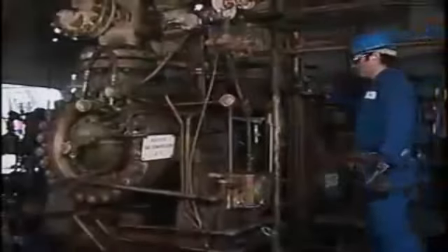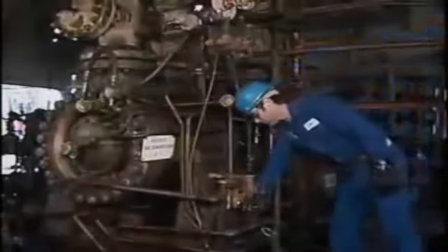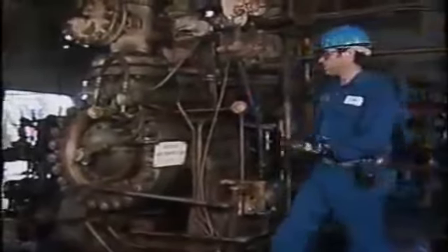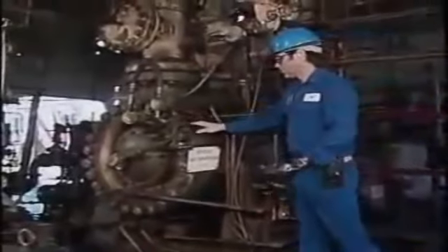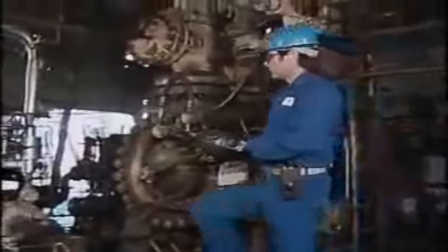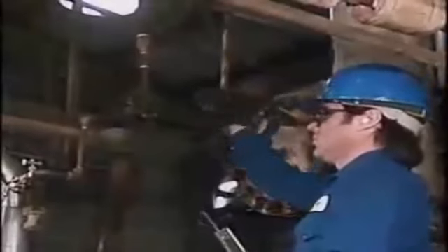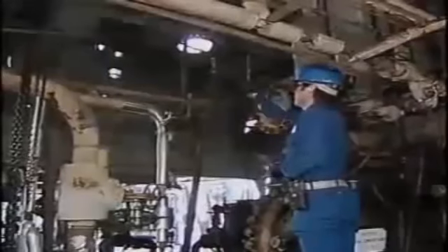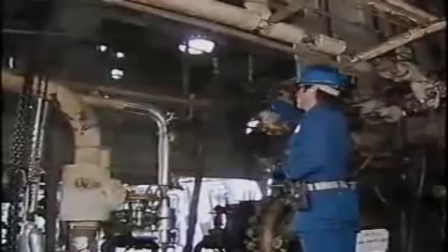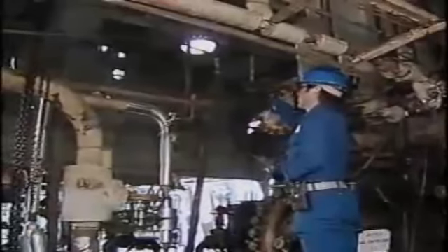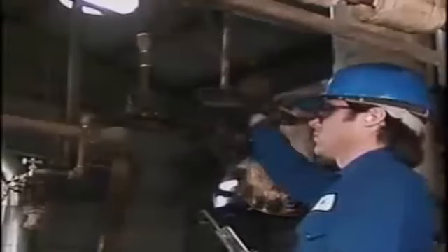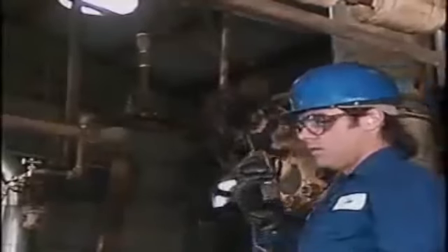One way to do this is to make sure that the oil is at the proper pressure. In addition to starting and checking the auxiliaries, the operator also checks the compressor to make sure it's ready to be started. He checks the equipment for abnormal conditions, such as loose or missing parts. This compressor is driven by a steam turbine. The compressor handles a flammable gas, so it must be purged with steam or an inert gas, such as nitrogen. The operator does this by opening a manual purge valve. Purging removes air from the compressor and reduces the risk of an explosion or a fire.